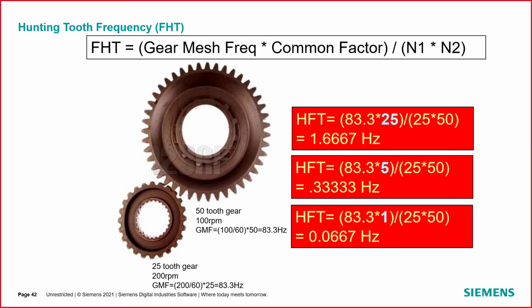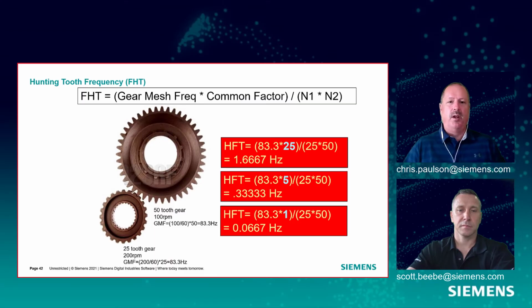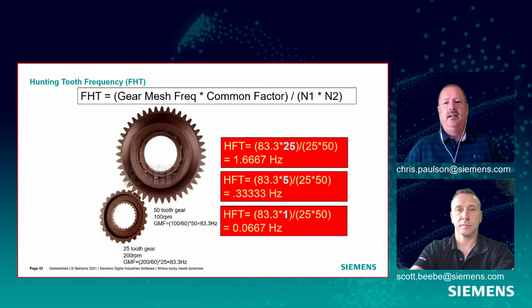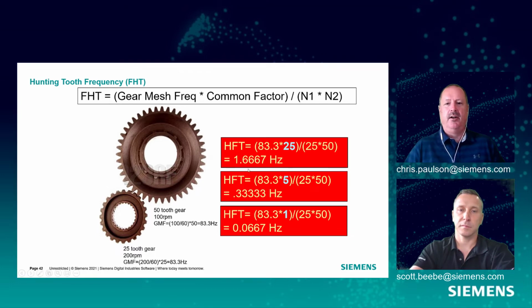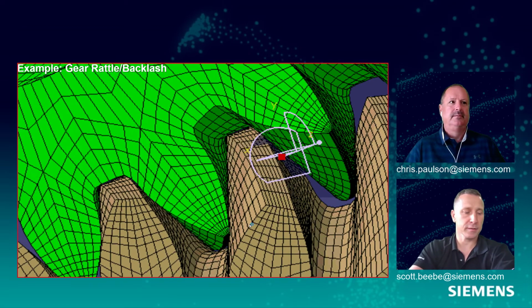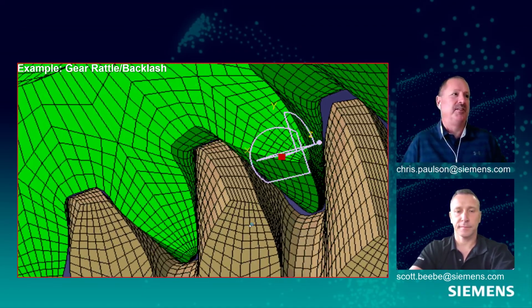So if we're doing condition monitoring, checking out a transmission system, and we see spikes in our FFT at these frequencies, then we know that we've got a damaged tooth in the system. We may need to look at an early overhaul, etc. Yep. And it could be any of those frequencies, right, Chris? Exactly, any of those frequencies.